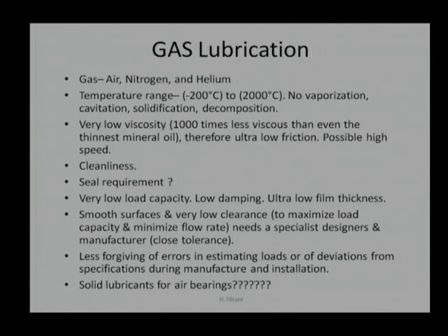These bearings are highly optimized. Once we have a thorough understanding of the complete system, load, speed, temperature, variation in the load, variation in the speed, then only we should utilize an air bearing. Talk about the rheometer, where we want to find out the actual measuring torque, or the torque resistance given by the fluid. We require extremely good bearings. In those situations, these air bearings can be utilized.